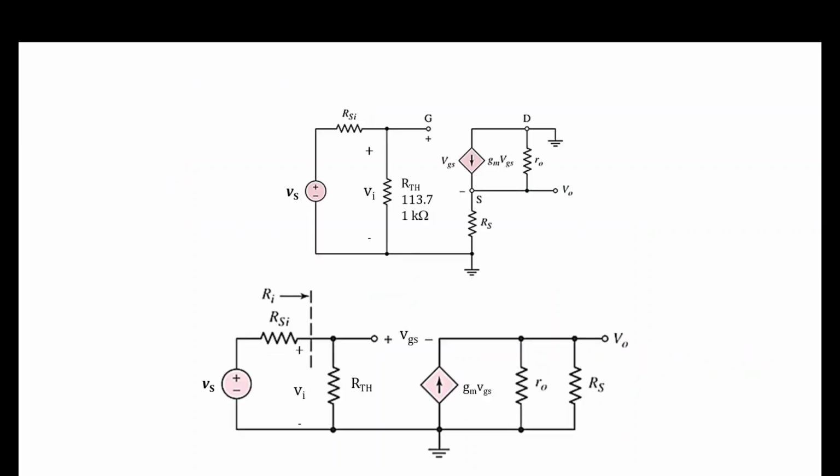So this is the original AC equivalent. You can see over here the V out is measured at the source terminal. Similarly, you are going to rearrange so that V out is on the right hand side. So I bring my RS over here. You can see this is V out connected with ground. This is my source, so this one is done. Then R0 is connected between source and D, and because D is grounded, this is ground.